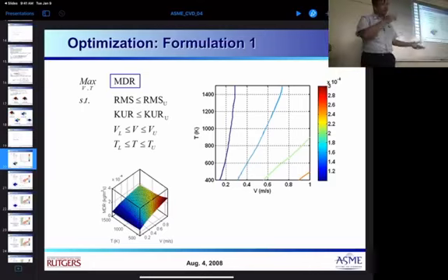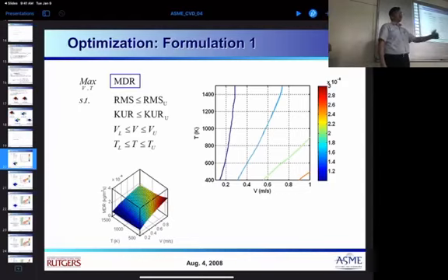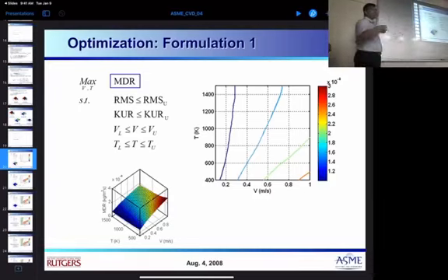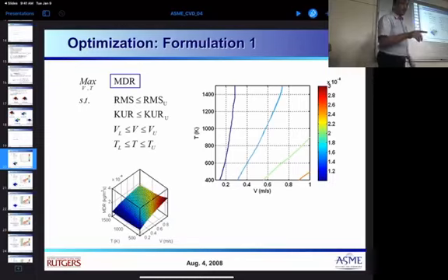So, like I said earlier, I not only want to have the maximum speed of my production, I want uniformity. So in my Fluent, I have a deposition profile. I analyze the uniformity, make it a number. So for every experiment, I have a number representing uniformity. So RMS is the root mean square error. KUR is so-called the kurtosis.